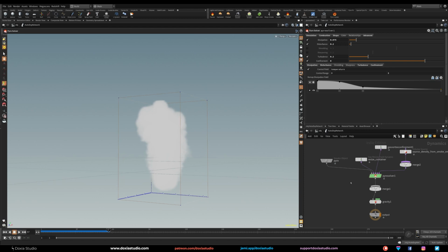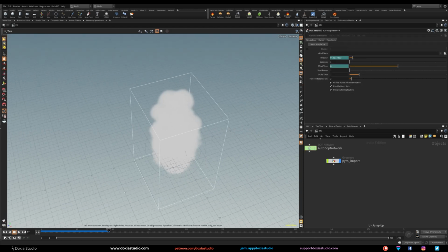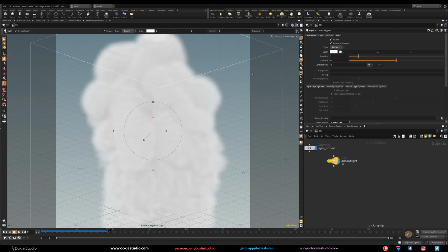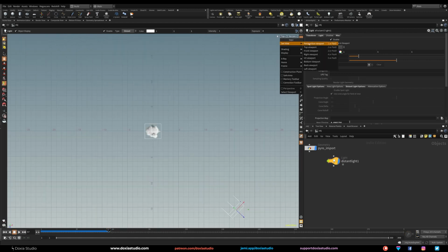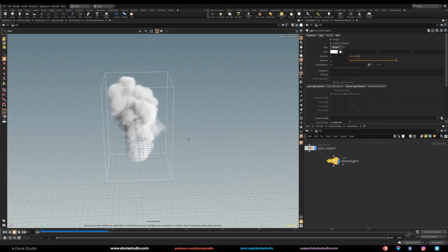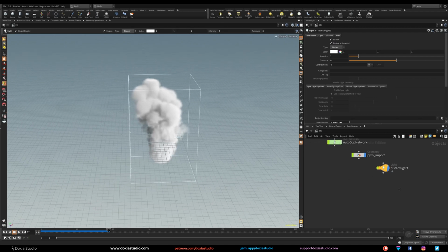Let me add a light so we can see a little bit better. Let's put the viewport like this, go to lights, Control-click on distant light, create on the same angle as you did on the viewport. Let's go to top view and now back to perspective. Space, Shift H to see everything. Now we can see our volume a little bit better, right? Let me organize this a little bit. So this will be our smoke, and let's go with smoke out.